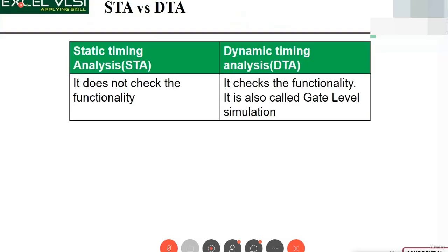From Hyderabad, leaving the city itself, I take this much time. City 1, what is the time? City 2, what is the time? Then near Bangalore, near the airport, right? So like that, splitting the whole path into multiple timing arcs and analyzing and making sure that you reach at the right time you budgeted.